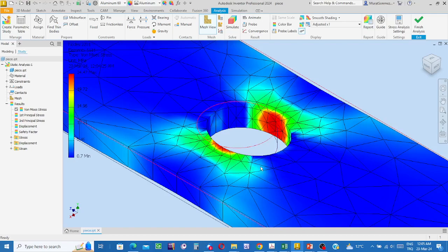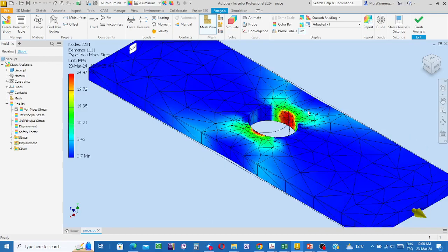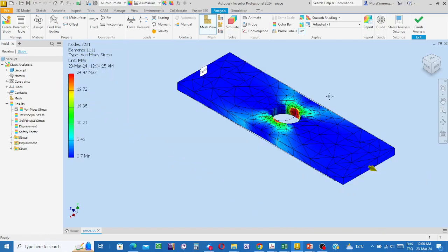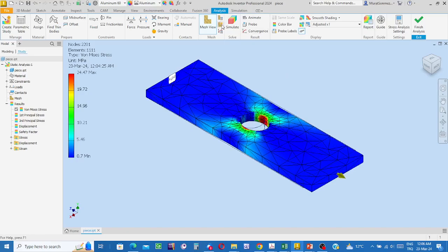We have more elements, so the result of the calculation in the vicinity of such a discontinuity is more accurate. Okay. This is one of the techniques. The other technique is, under control, not making iteration, using local mesh control, we can use a smaller size mesh.